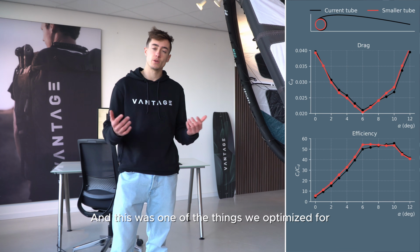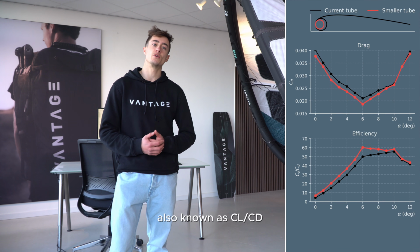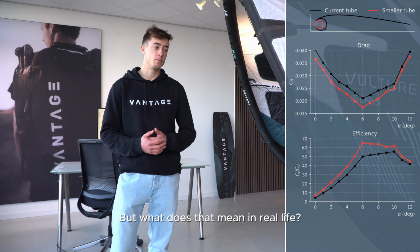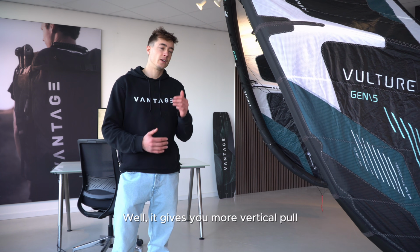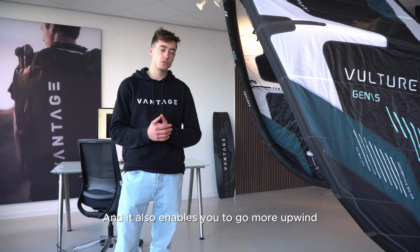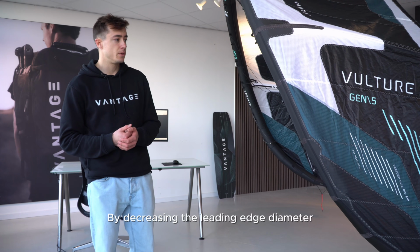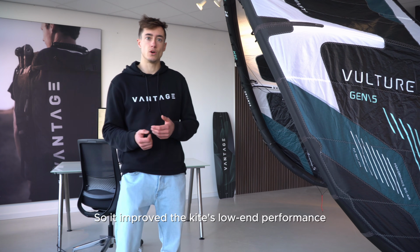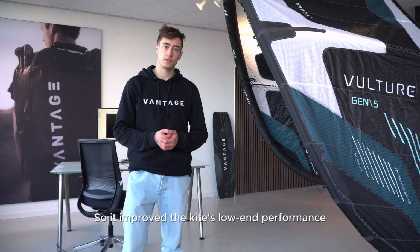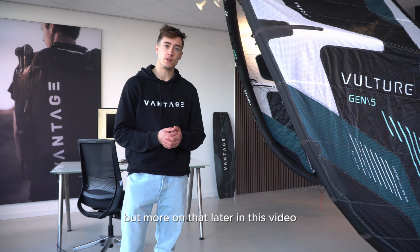And this was one of the things we optimized for, increasing lift over drag ratio, also known as CL over CD. But what does it mean in real life? Well, it gives you more vertical pull, less downwind pull, and it enables also to go more upwind. By decreasing the leading edge diameter, the weight also decreased, so it improved the kite's low end. And the kite became also more responsive, but more on that later in the video.